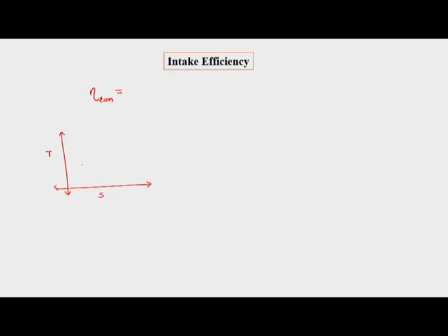So, we know that in case of gas turbine, we have the Brayton cycle first. In the Brayton cycle, we first have the compressor, which takes 1 to 2 as isentropic compression, and then we have seen that if the compression is not isentropic, it does not go in the vertical direction, but leads to some other point.